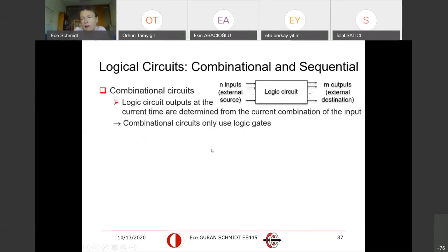Okay, now we learned that there are 2 types of circuits, combinational and sequential. So the combinational circuit was the outputs only depend on the input, and the outputs are produced immediately when the input is applied after the signal propagates through the gates, okay, without any more wait, whatever the gate propagation time, how many gates you have back to back, but the output is produced.